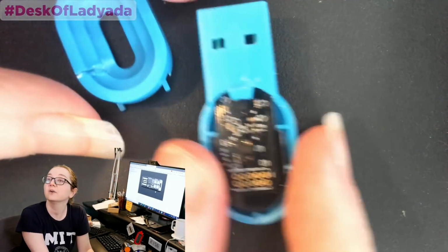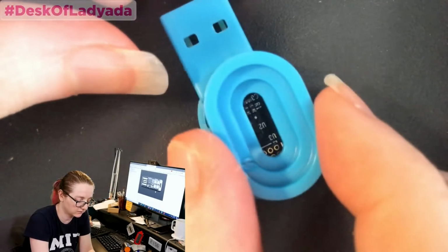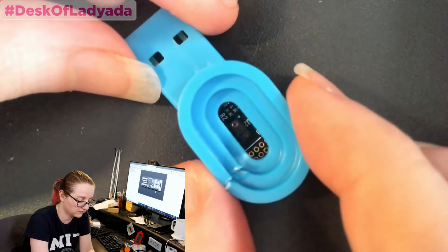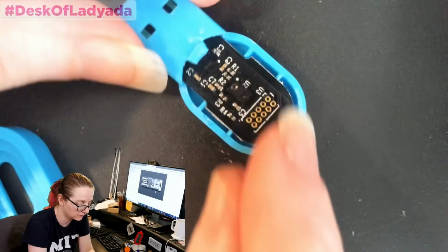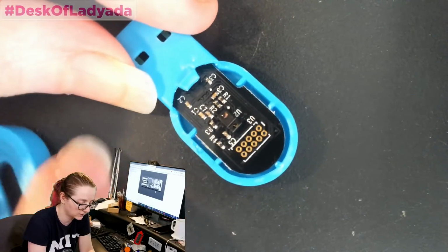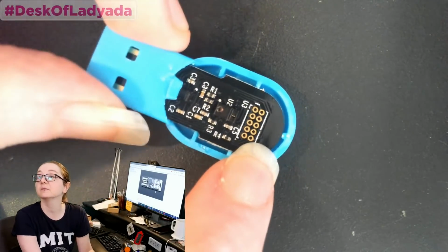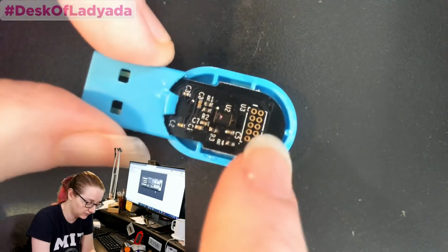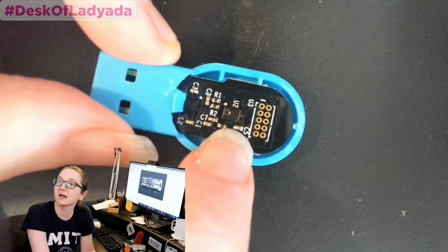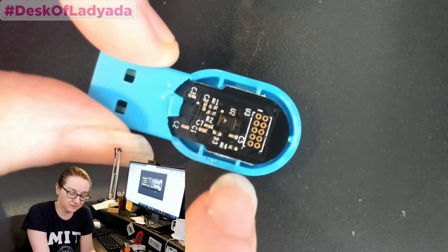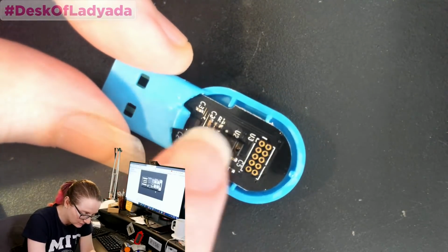Cool. So if you pop it, this thing doesn't really do anything, I don't think. It's just a little protector, and I pulled it off. I also kind of cut this down the side. I didn't realize that was not essential. You just pull this off instead. So you've got your SWD pads here. It's a very classic 2x5. Here is your APDS 9960. It looks just like an APDS 9960, that's how I know what it is. I've seen this sensor many, many times.